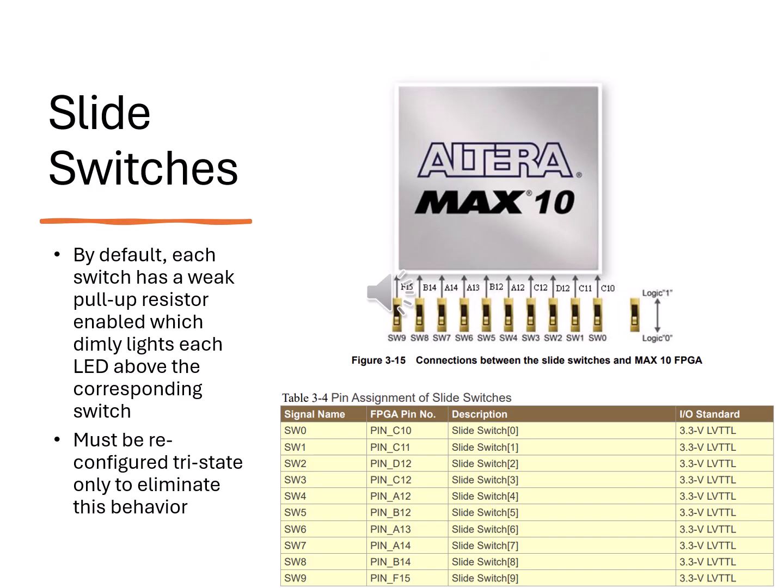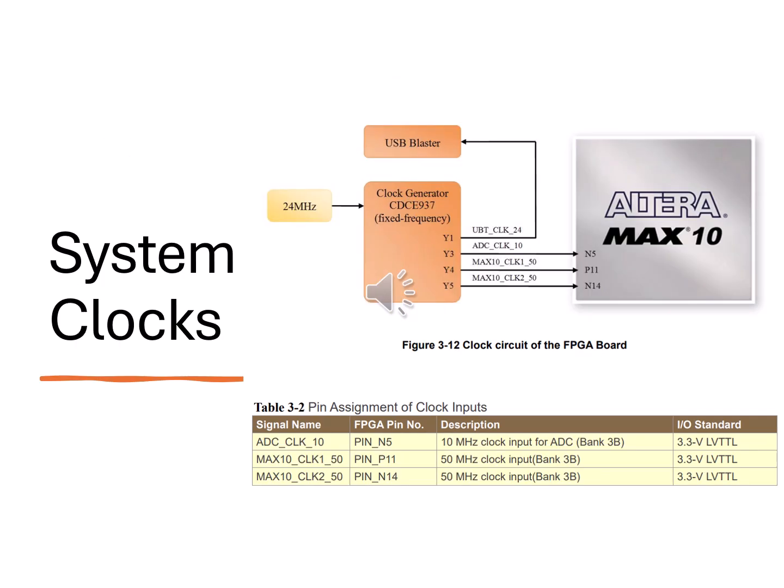Slide switches behave a bit differently. They have a default weak signal which can cause LEDs to glow faintly, but with proper configuration you can eliminate that and get clean logic behavior. The board comes with system clocks, signals that help synchronize your design, kind of like a metronome for your circuit.